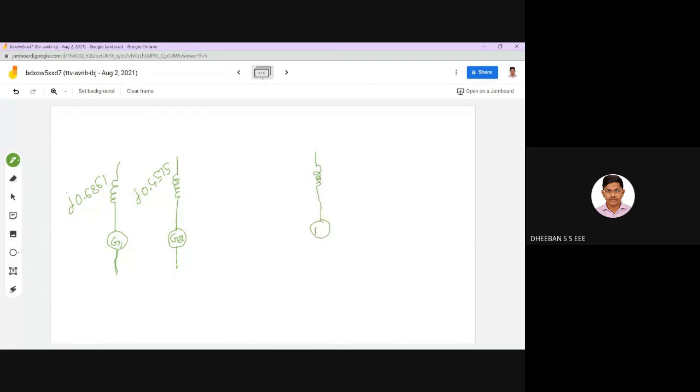Okay, so after this, for your motor, the motor will be on the load side, but it is in parallel. It will be M1, and this will be j1.026, followed by motor 2, M2. It will be j0.6837. So we have drawn the equivalencies. Now we just have to connect it. Okay, and this represents your reactance diagram.